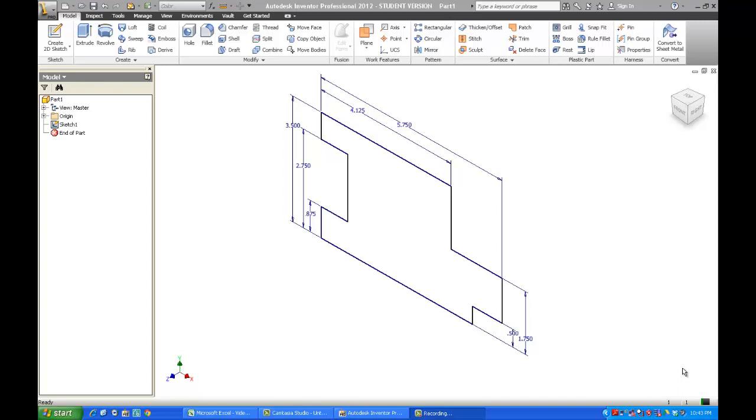Right now, we're going to show you how to use some of the geometric feature tools, or the modeling tools. Right now, I've got a fully defined sketch on my screen. What you're looking at is a sketch that I have gone in and created, and then I've applied dimensions to control it. I've applied constraints to maintain parallelism, or vertical or horizontal straightness on these pieces. Now, what we're going to do is show you how some of these tools work.